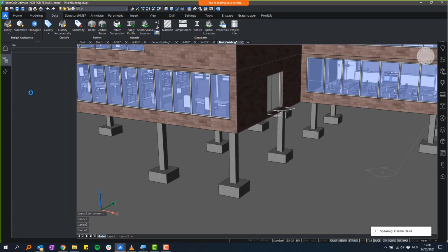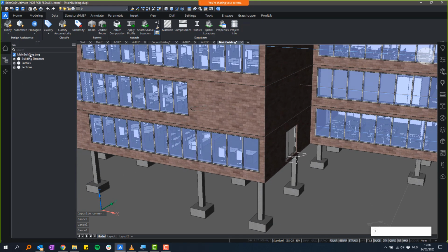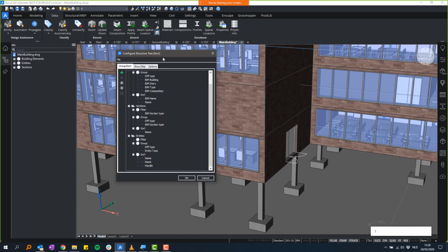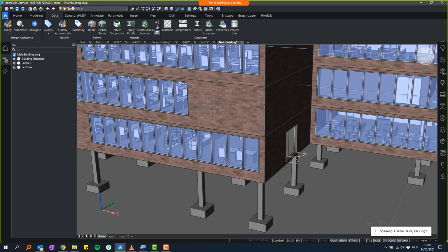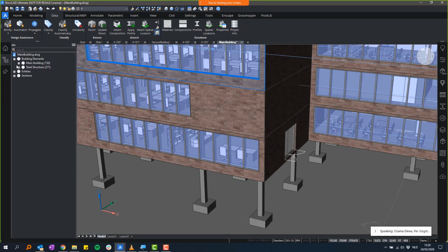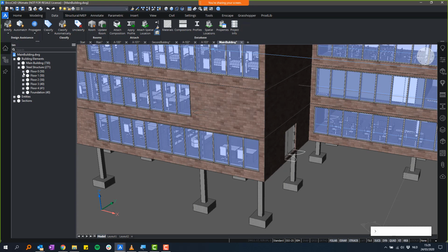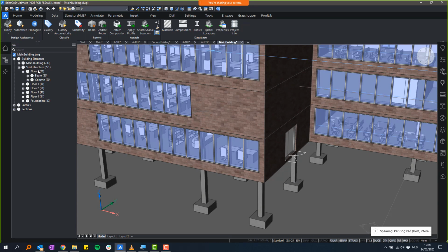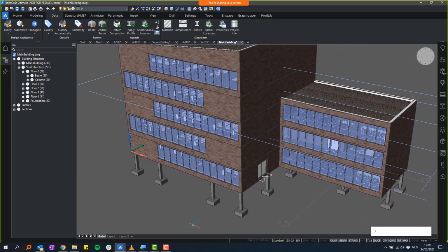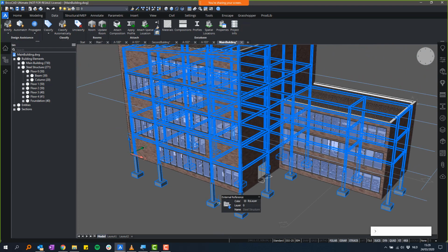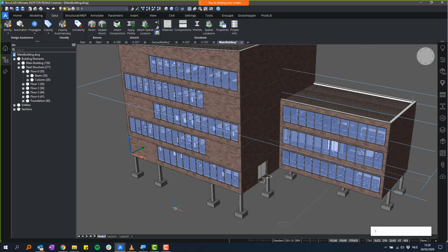And also, in the structure browser, there's this option to explode XREFs in a tree. So this will mean that I will see all my separate objects, my steel structure. I know I have 30 beams on the floor zero, for example, or 20 columns. Even though they're part of this one XREF, it's still kind of exploded in this tree view. And also when you're extracting information, like using data extraction or scheduling, it's also possible to go inside these XREFs and extract this information.